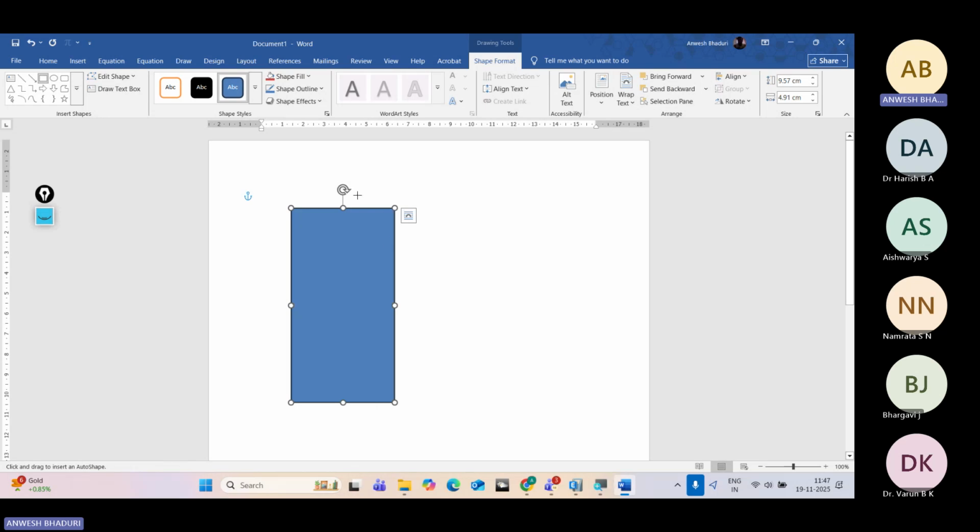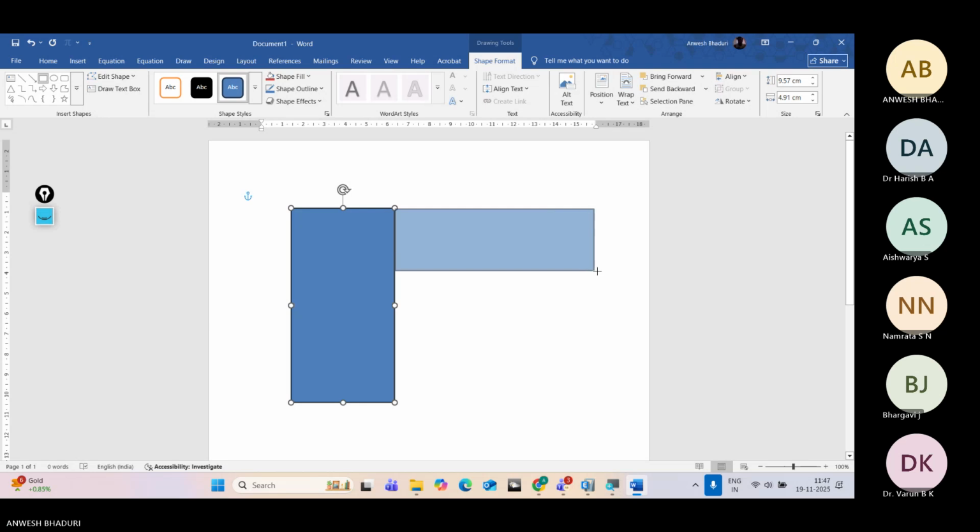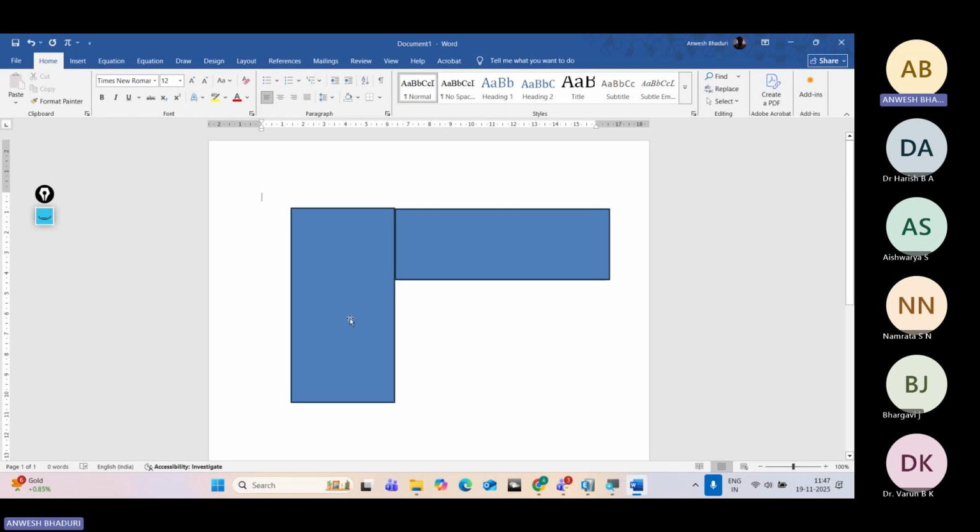So if you are in a plan view, if you are seeing a column like this and your beam is joining like this to your column, then there's an offset from the centroid of the column object by some distance.